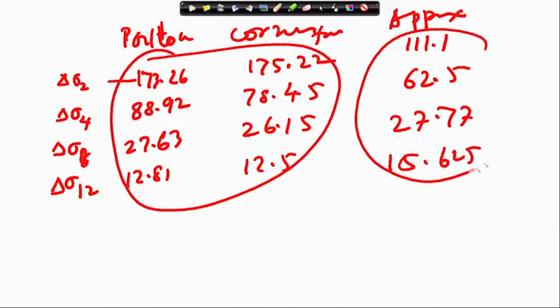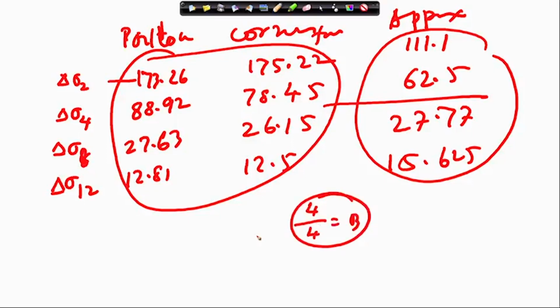There is a little error up to 4 meter. Here 4 meter is actually nothing but B, if I consider the dimension 4 and depth is 4. So, up to depth B the approximation is not very good, but beyond B, that means at depths greater than B, the approximate value is also quite close to the rectangular corner formula and point load formula.